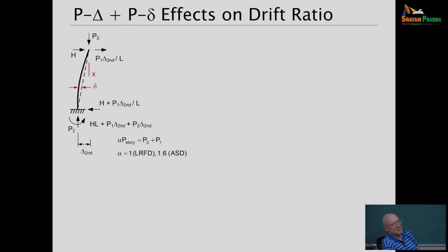So if there's no axial load, there's also no P small delta because there's no P. The chord is between the deflected member ends, right? And because we have bending in the cantilever, the reference axis of the cantilever is offset from the chord at different positions along the length. If it's just a horizontal load, then yes, it's a sway problem. If there's no P, there's no P small delta, correct?